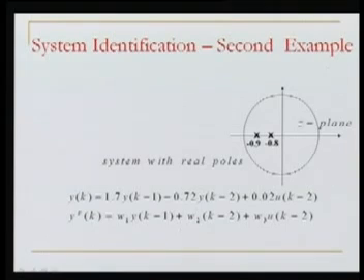We take another example today, where we have two poles within the unity circle, but they are all real poles, minus 0.9 and 0.8, and this is my system dynamics. My model is y_p(k) = w1 y(k-1) + w2 y(k-2) + w3 u(k-2), so I take the same single neuron with 3 inputs: y(k-1), y(k-2) and u(k-2).